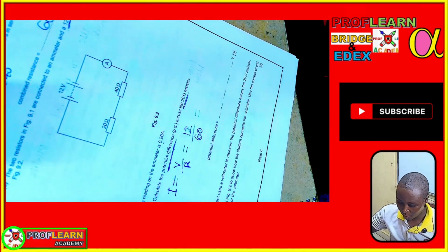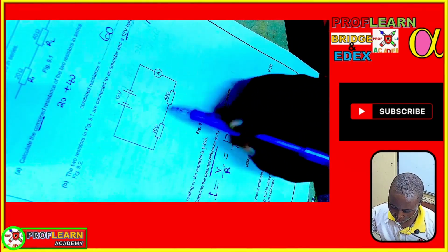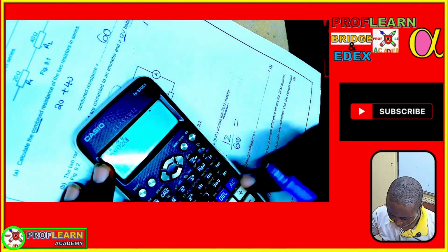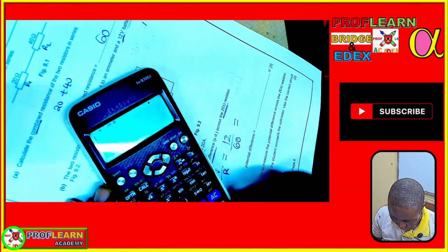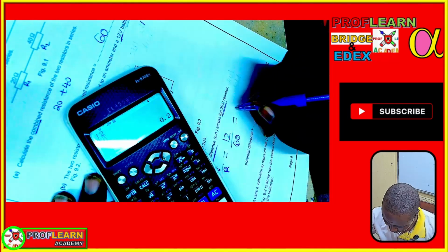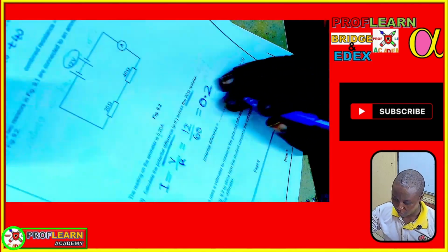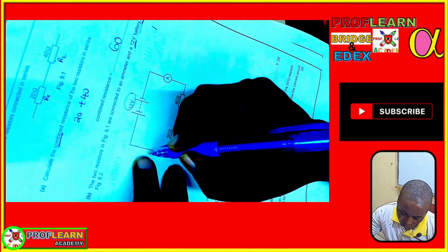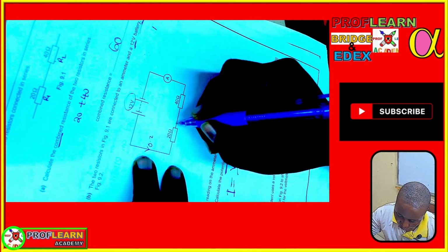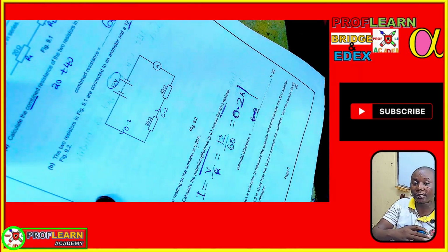Yeah. So the total resistance of this circuit is this plus this, 60. Then the voltage is 12 volts. To get the current is voltage over resistance. This is going to be 12 over 60, and that translates to 0.2. And since this circuit is in series, the current that is going to pass here is 0.2, and the current that is going to pass here is also 0.2. For a series circuit, current is the same throughout.